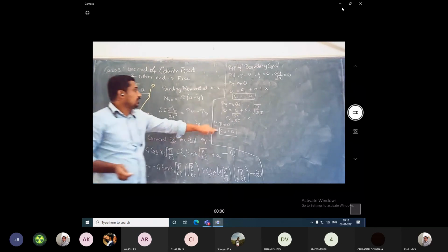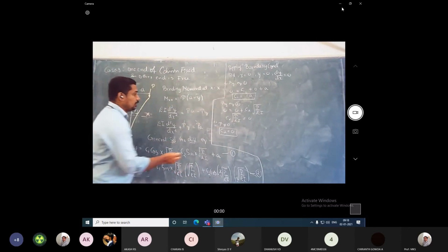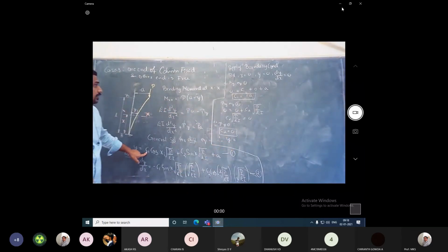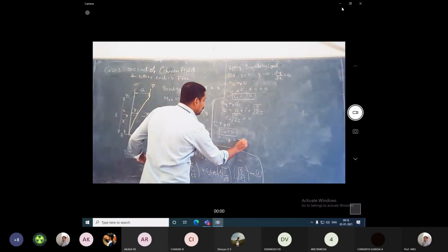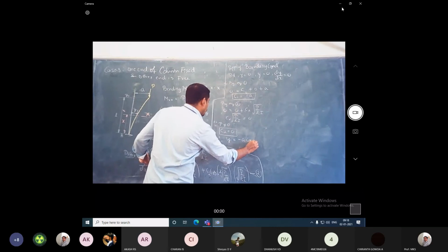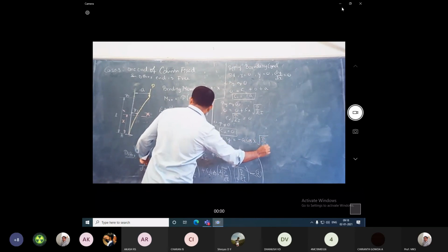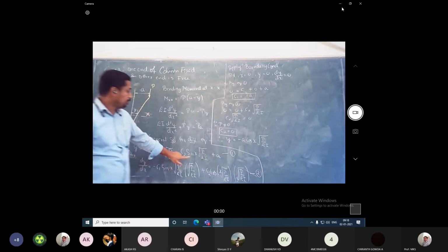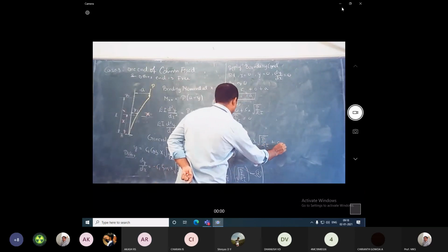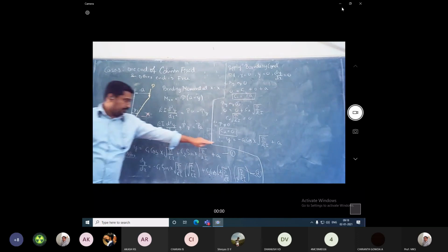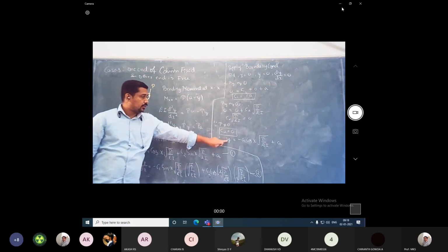So next you apply this C1, C2 in equation 1. Therefore, y will be equal to, C1 is minus A, so minus A cos x root of P by EI plus the C2 term is 0, plus A. Okay. So by applying the boundary condition at the point A, I got the equation which is reduced and I have found the constants C1, C2.